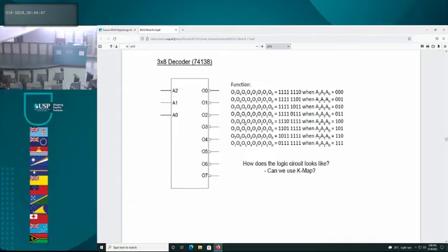Because there are 3 inputs, how many possible rows, guys? 8 rows, 2 to the power of 3. Where did we get the 8 outputs from? Well, you look at the chip; the chip has got 8 outputs. So you then populate the truth table, and from there, for each line of output, you will get a different equation. So you'll get 8 circuits.